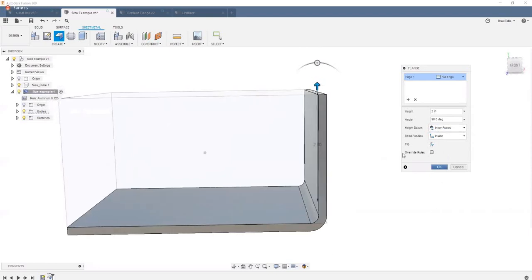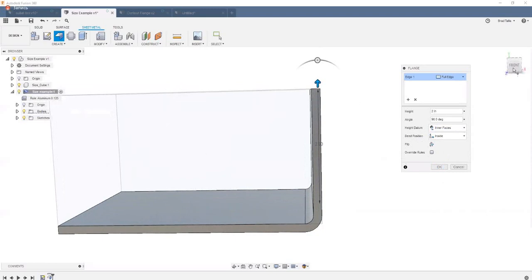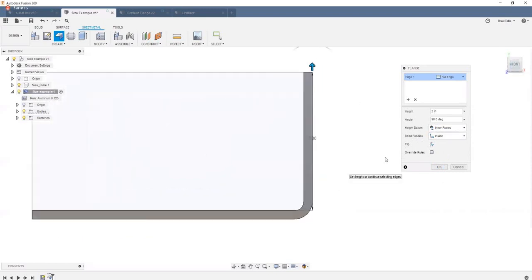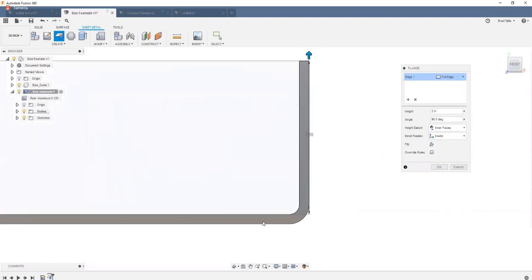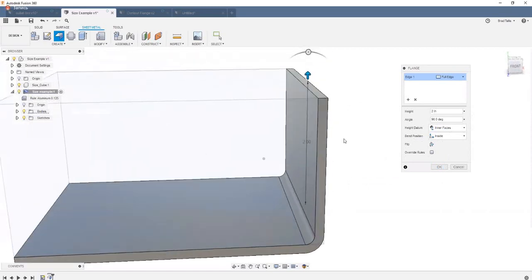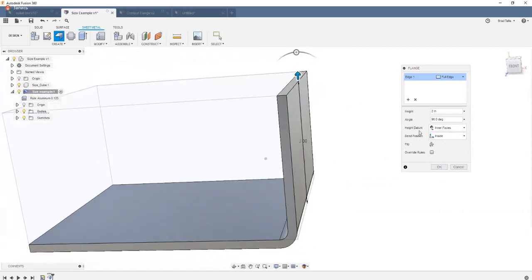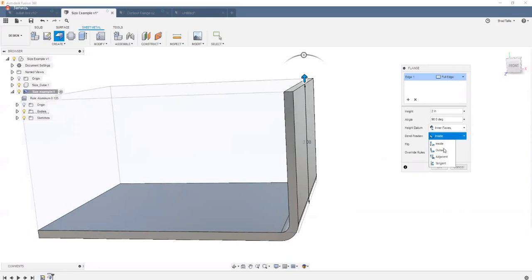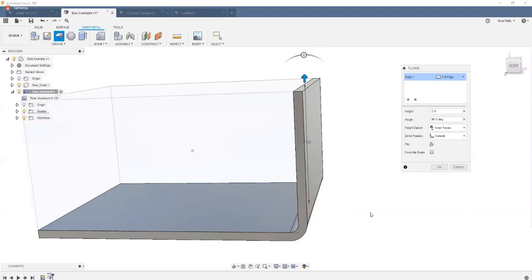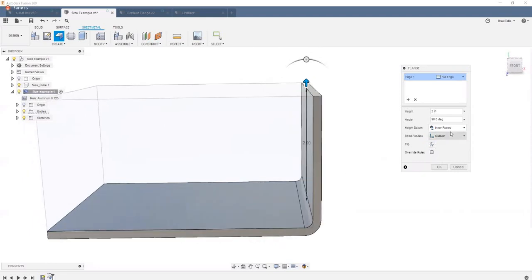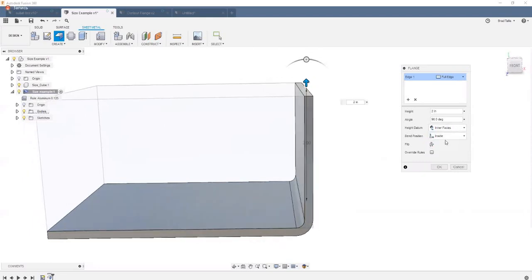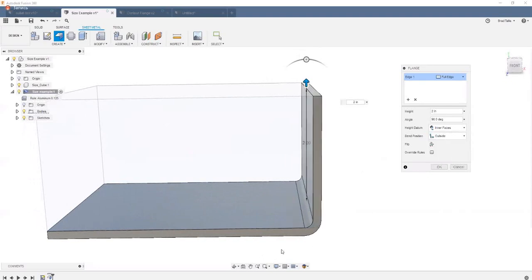And then you'll notice it says bend position is set to, actually just look at it straight on, is set to the inside. So it's actually bending, oh, maybe it's better in 3D, sorry. It's bending to the inside of that box. If I say outside, we can now see how that jumped from the inside to the outside, okay? And it's perfectly touching our blue box.